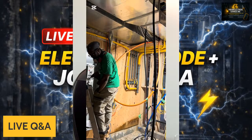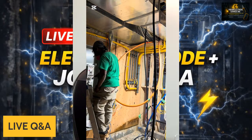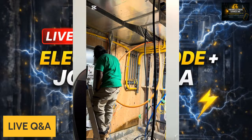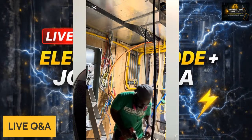And again, what we simply have here is a 400 amp installation of the main panel using 250 kcmil parallel feeds to power up this unit.